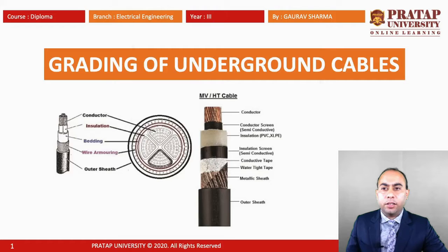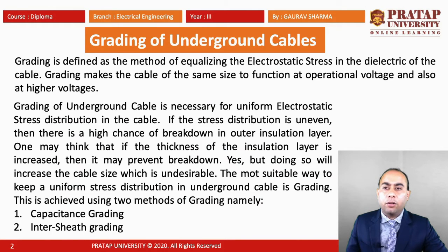Welcome students. Today our topic is grading of underground cables. Now grading is defined as a method of equalizing the electrostatic stress in the dielectric of the cable. Grading makes the cable of the same size function at operational voltage and also at higher voltages.